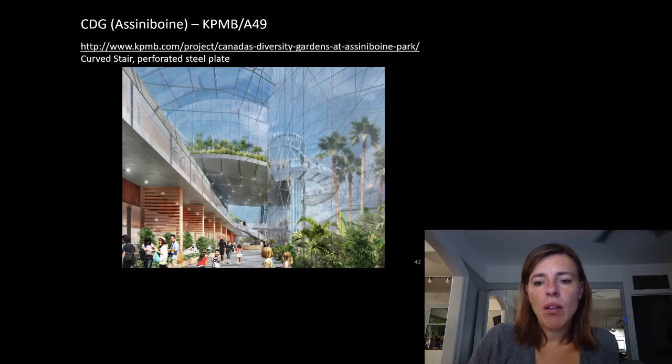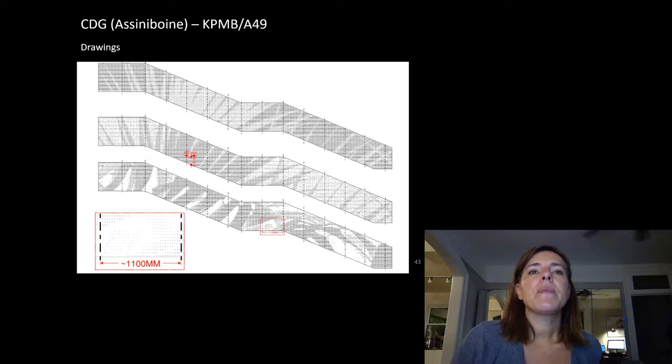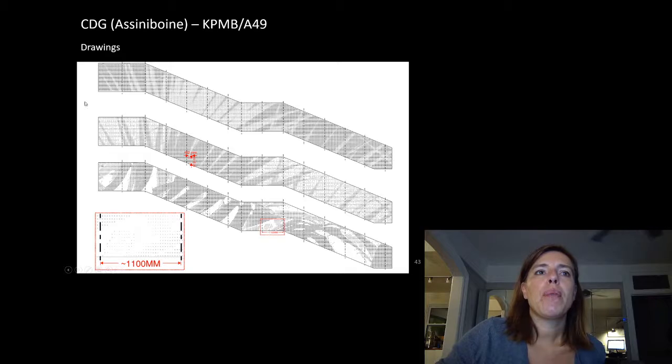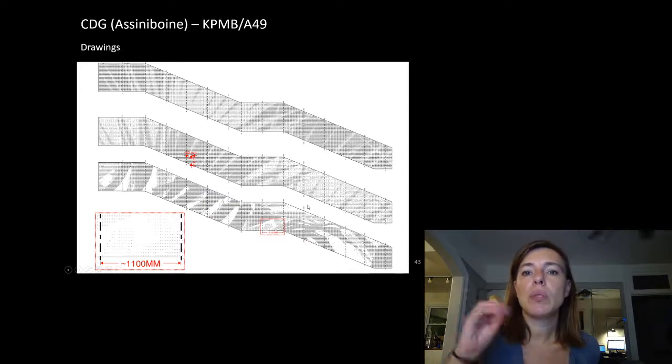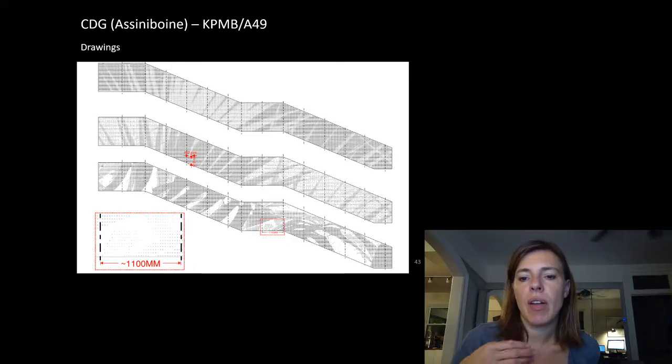Assiniboine, I've shown you this one already too, so I'm going to start to go through it a little bit faster. I didn't want these lectures to be longer than an hour and a half to kind of add up to the 3-hour kind of total. This is what I was given for the mesh panel here. When I did this, I looked at the spots where they had the most material removed and saw what the equivalent of that was over a similar area. So what the equivalent thickness would be for the entire cross-sectional area or the entire volume of that element.